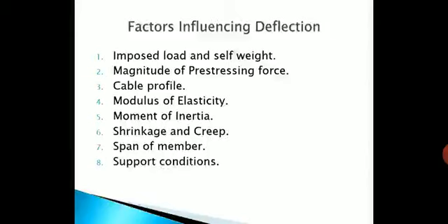Now, imposed load and self weight. Of course, the major factors which cause deflection are the loading, or say the gravity loadings, in which the imposed load and the self weight play a major role. So here we see the importance of structural design. Self weight of the member is by virtue of the dimensions of the member. If a member is properly designed, we can have optimum dimensions for the member which optimizes the self weight. That's where proper structural design comes into the picture. The imposed load depends upon the type of structure, and that consideration is taken in the design.